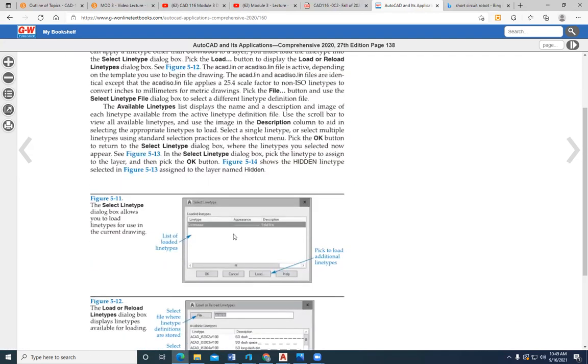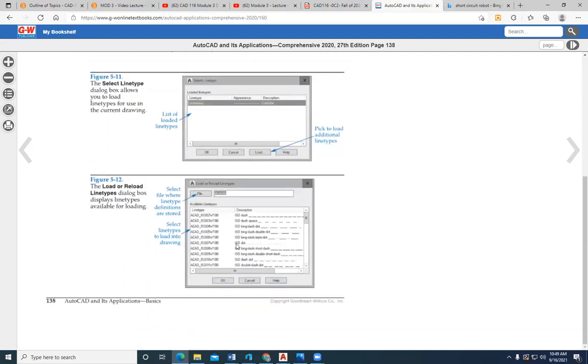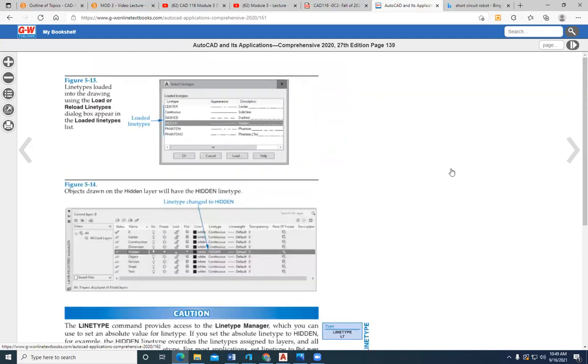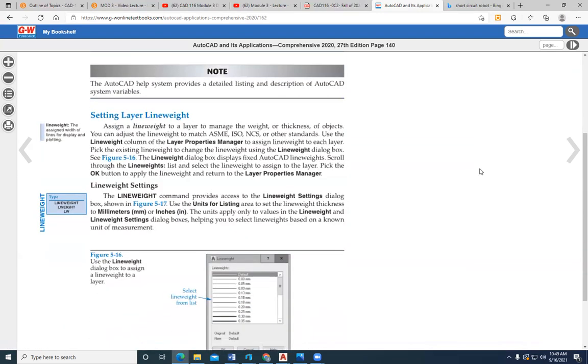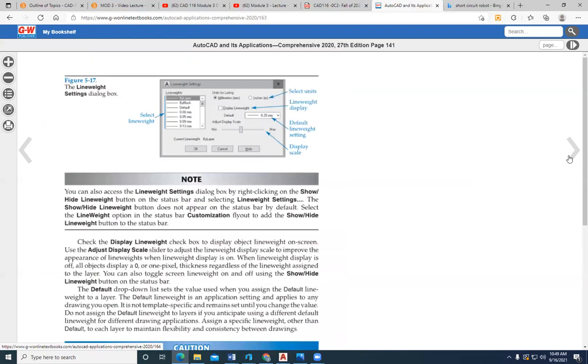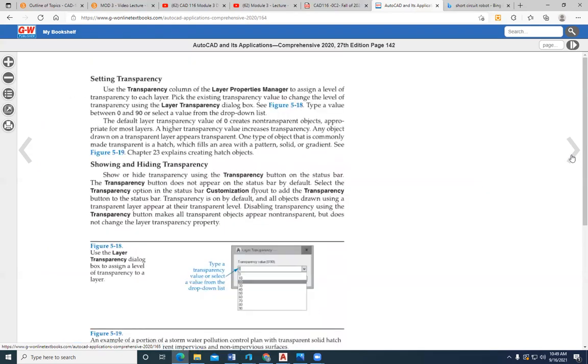And then line types. Different line types mean different things. So hidden lines convey things that are behind other features. Object lines are in the front. Phantom lines convey motion in different positions. And their line weights then are set towards the standards for ASME Y14.2.